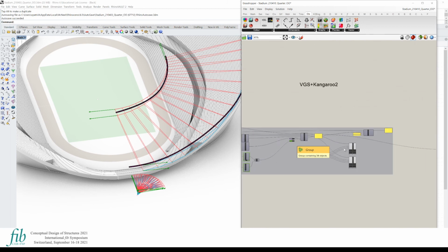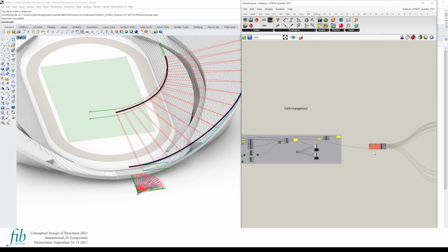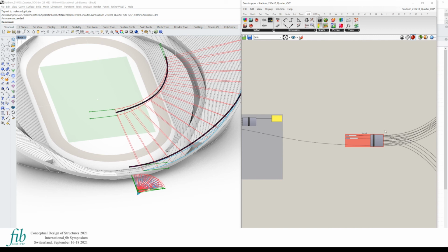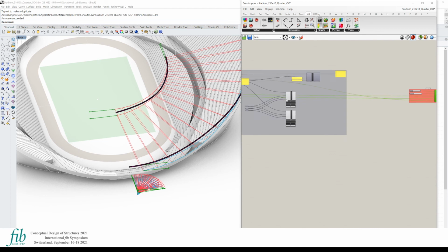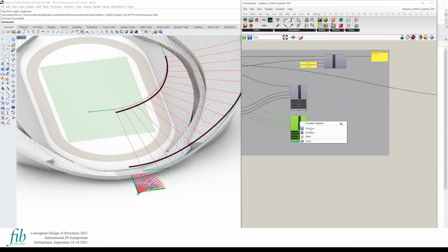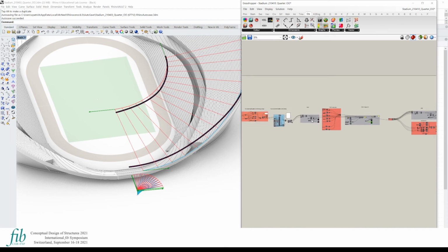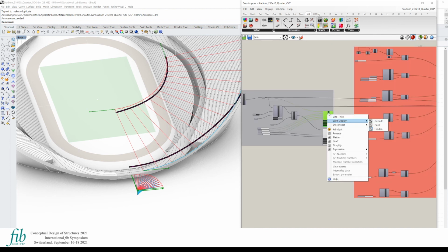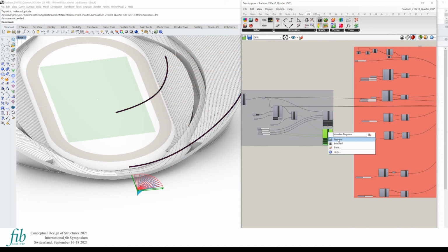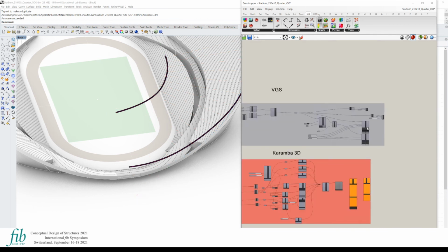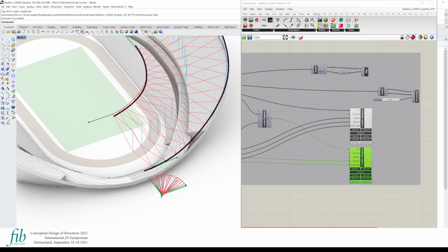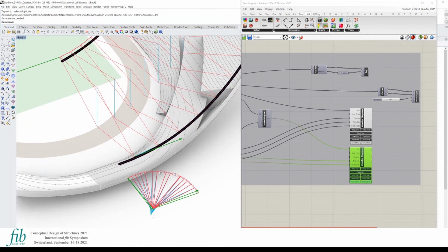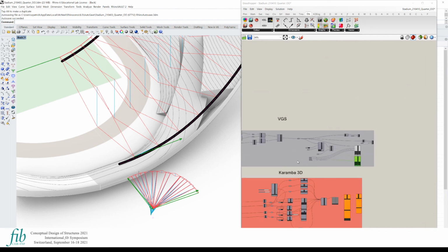In this case, we take this form-found quarter and modify it. We replace each spoke with 4 cables and 1 flying column, which you will see in a short second. Before this, I turn off the form and force diagram visualizations so as not to have too many diagrams overlapped. Now we have an empty canvas, and we can activate the new form diagram and the new force diagram. You see it here, a little bit more complex, where we now also have some additional vertical struts that we also see in the force diagram.